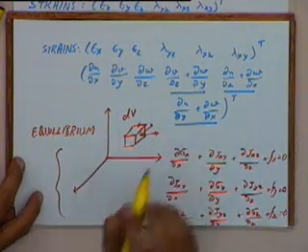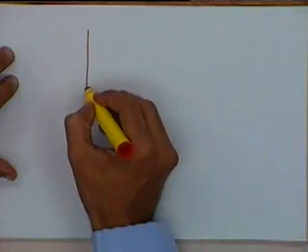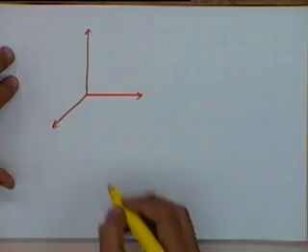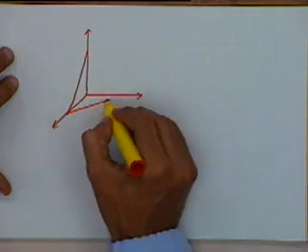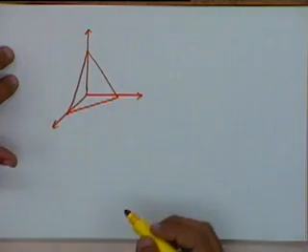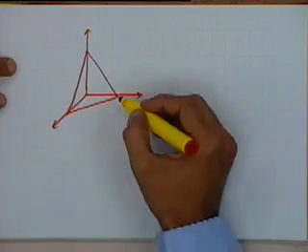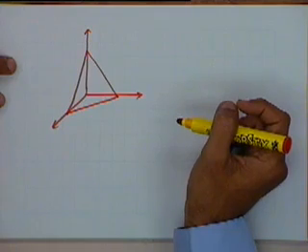in an elemental body element, or in a cubical body element. Similarly, if you take an element which is on the surface, it will look like this. If you have a 3-dimensional surface, a curvature, and we are taking an element which is on the surface, it will not be cubical, but it will be somewhat pyramidal, or a tetrahedral element like this.